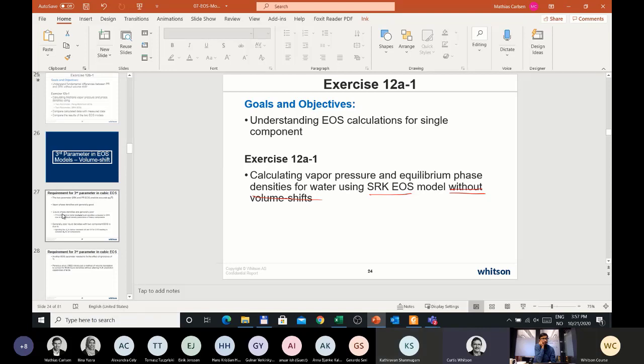What I would just call single phase, you're calling the dense phase; basically at high enough pressure, it's single phase. Single phase, high pressure gas or oil won't be predicted better by the SRK or the Peng-Robinson consistently. I don't believe anyone's shown that, and I wouldn't prefer one over the other.